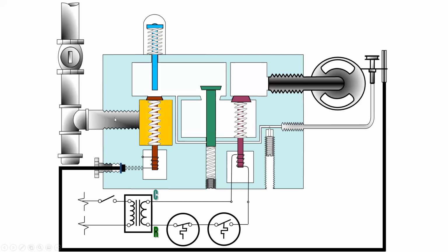And what we see is that there is now gas that has filled this initial chamber. Now, the thermocouple needs to be hot in order to allow for this valve to be in the down position. And if we want gas to flow through to the pilot burner, we need to somehow allow it out of this small chamber. And this is the reason for the manual push reset button. The manual button is used with a finger to depress and allow gas into the main chamber. So what we're going to do is press it down.